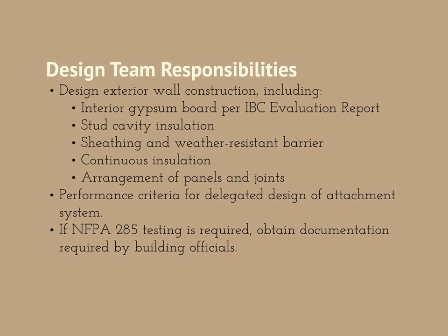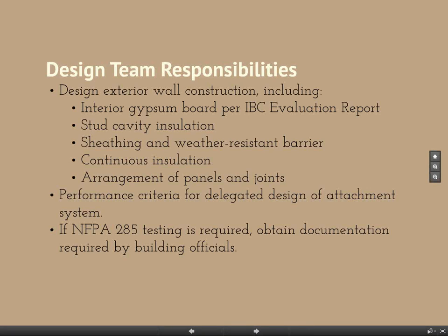Right. And according to the folks I talked to at ICC, and of course they won't come out with any kind of a formal response to this, but in a call-in arrangement, they're saying that yes, it is intended to eliminate the Z-girts because it must be continuous, but there's nothing in the code that actually says that. We have a couple of questions that relate to this slide. Sheldon points out, look at Cascadia clips. They're used as a standoff for the furring.